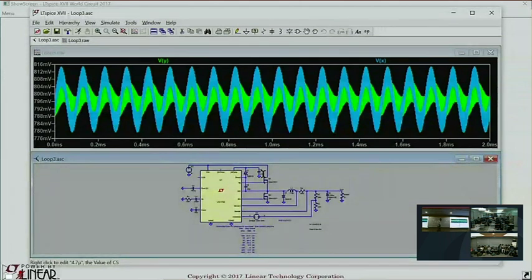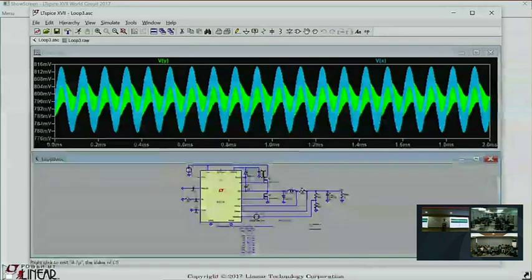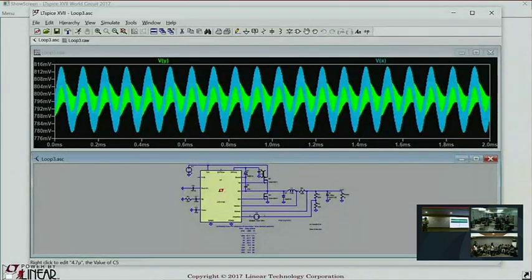Okay, now, you will find people looking at this in the frequency domain, and the reason is because they can't understand the nonlinear circuit. They say, okay, what we'll do is we'll get everyone in the design review meeting to agree to only discuss frequencies well below the switching frequency. And then you can build the linearized model of this thing. Because well below the switching frequency, you can.